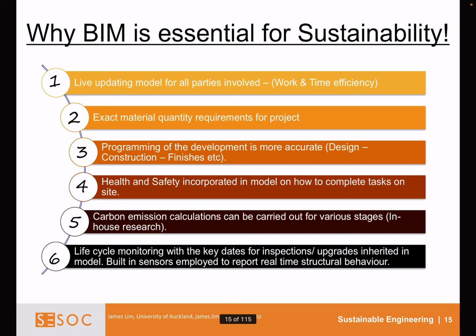And last but not least, life cycle monitoring. Monitoring of the development must be carried out over its life cycle. This can be done using remote structural monitoring by using sensors throughout the structure to monitor the structure behavior, deflections, deteriorations, corrosion, sway, etc. This will give indications of when maintenance, repair, or demolition is required. In-person inspections could also be carried out with the results inputted into the development live model.